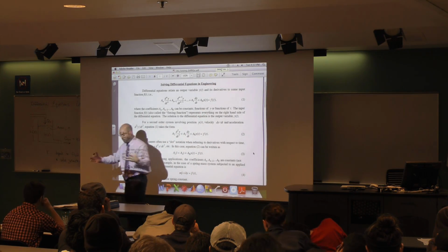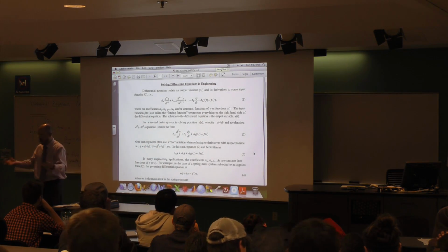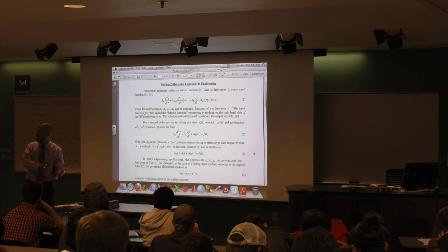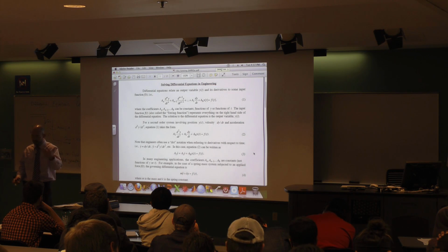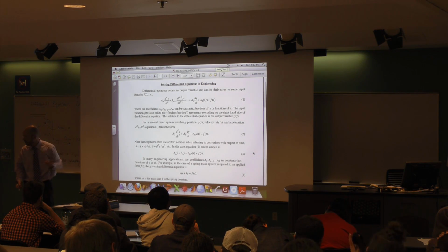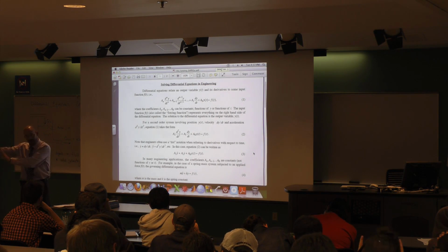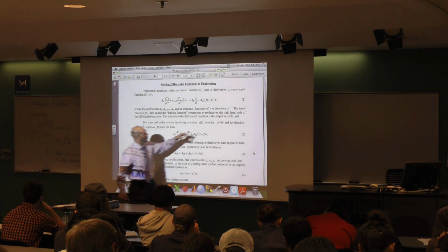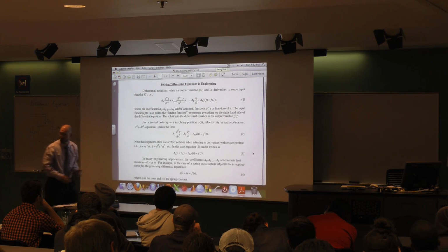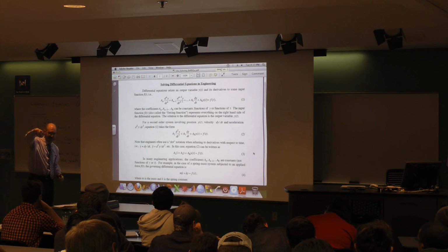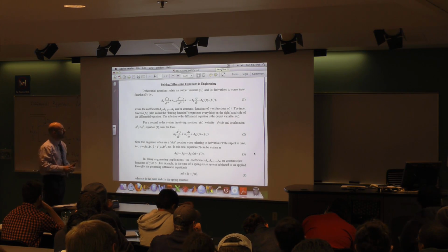So when you write down the governing principle and this physical equation, how do you know what's the left side and what's the right side? Whatever your unknown function and its derivatives are, that all goes on the left. Whatever's left on the right is your forcing function. In our case, that f of t is the q in. It's me turning the knob to make the volume flow in.